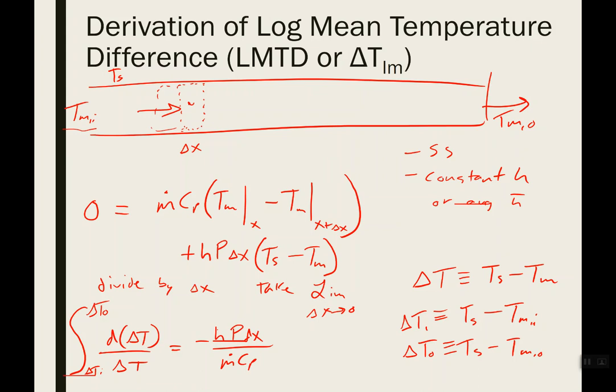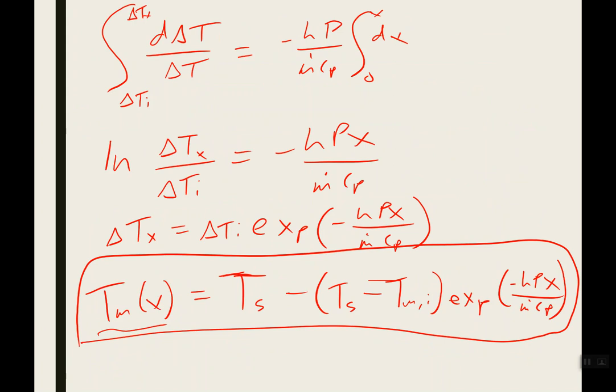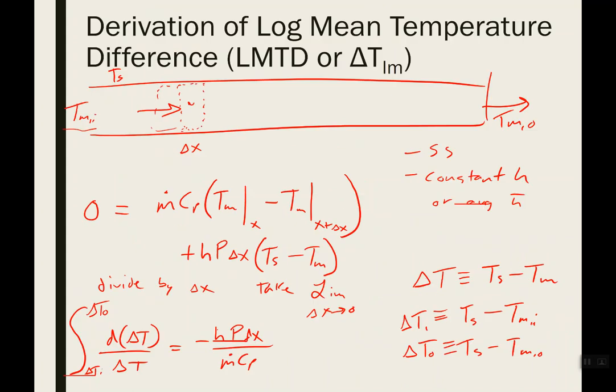If it's a really, really long pipe, that'll eventually get close to the surface temperature. But in the previous lecture, which I realized was like 10 days ago, we actually derived that. So we could use this equation and just plug in L for X, and that gives us our outlet temperature. Then we can plug that in here to get the value of this integral.